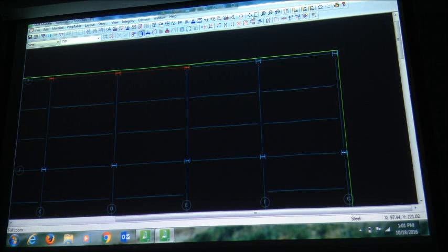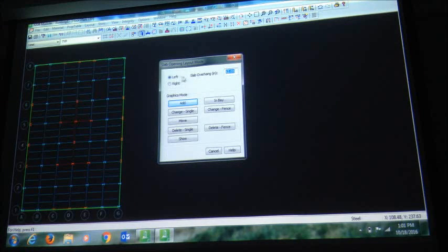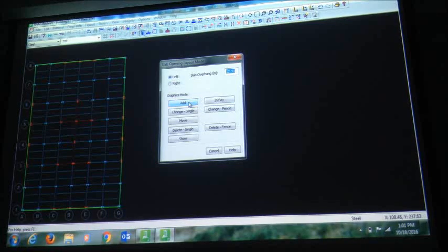Okay, click that. Now if I place the slabs now, the whole thing will be in a slab, but I need a penetration here, or an opening. So I will go layout, slab opening. Remember, I have chosen left overhang. It has to go from the center to 12-inch inside.